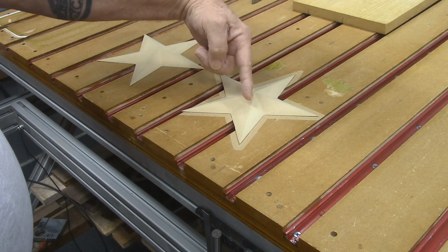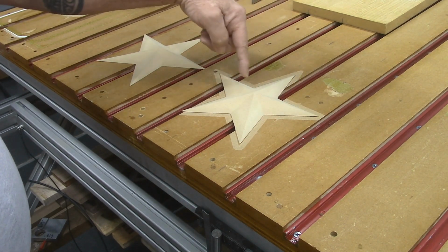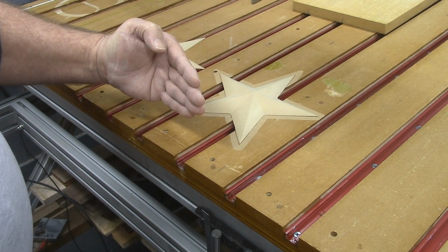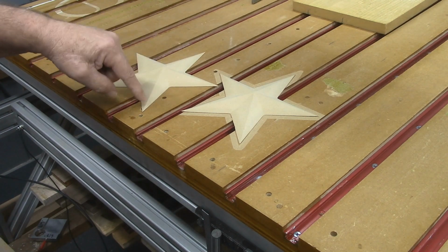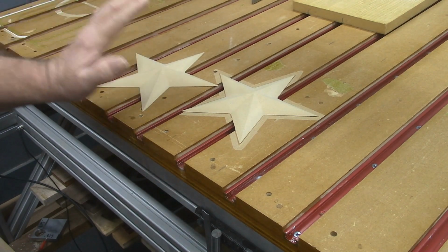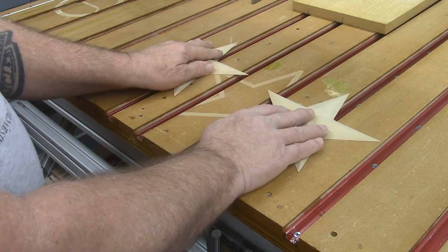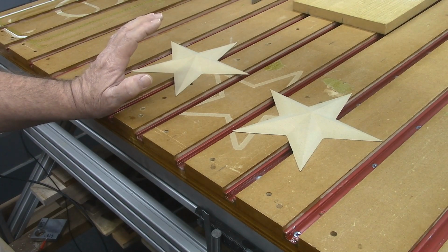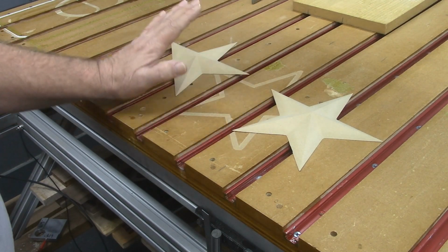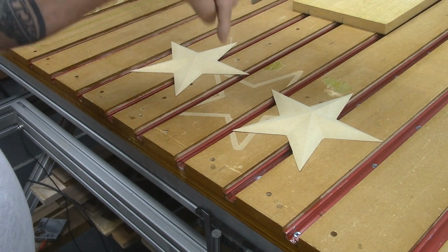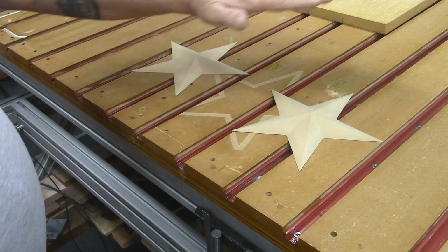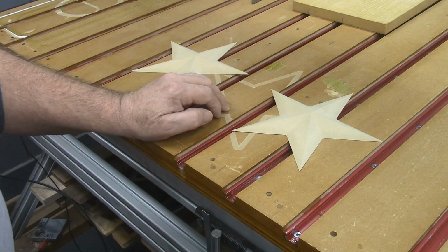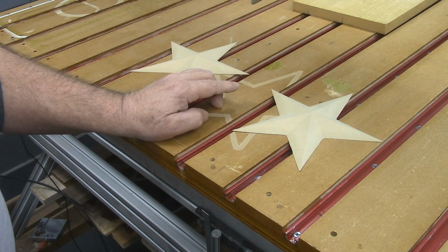So when it came down and started carving around here, it was actually in slightly from here. This is why we say when you are 3D carving, or V carving, or pocketing something that has to go down to a specific depth from the surface of that material, set your Z0 to your material surface.